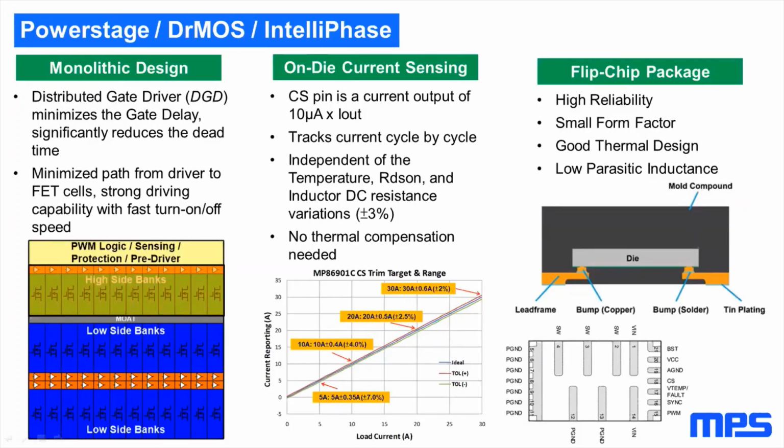Let's continue with the power stages. The power stages use a monolithic design. This means everything is on a single die. Typical other devices from competitors use multiple chips in a single package. Our technology allows us to reduce propagation delays as well as dead time.